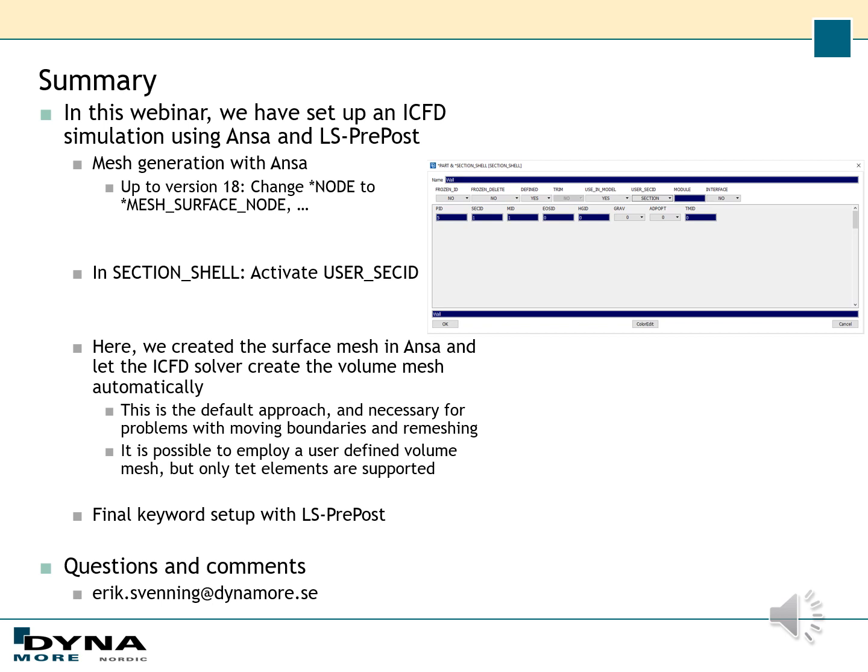So to summarize, in this webinar we have set up an ICFD simulation using Ansa and LS-PrePost, and a few final remarks here. First, regarding the mesh generation with Ansa, if you are using version 18 or lower, then you need to do some manual conversions, like changing node to mesh surface node in the mesh files.